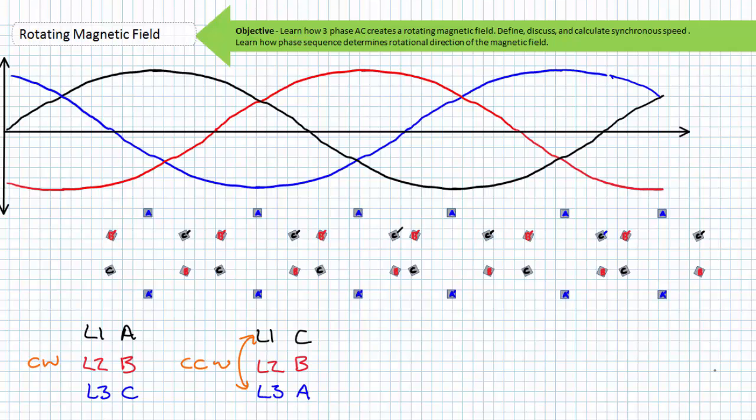If you want to go back to your original direction of rotation, just grab two at random and switch them again, even different ones than you switched the first time. You'll find your original direction of rotation returns. This is very important as numerous real-world applications.